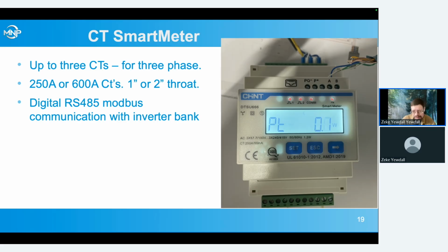So when you've got a 400 amp service and you're doing a stacked set of inverters on that, and you want to be monitoring that whole 400 amp service for purposes of zero export or supporting normal loads, you'll be able to get that around those usually parallel 4-aughts or parallel 250s coming into that 400 amp service. There's another workaround that we're also working on right now, but it'd probably be best to wait for the 600 amp CTs for that.